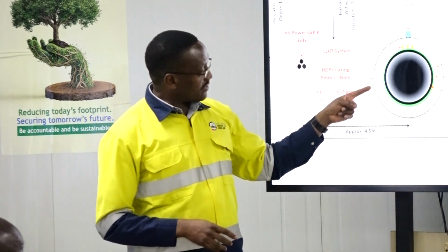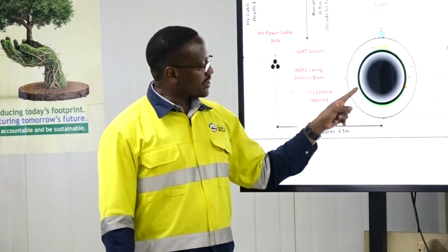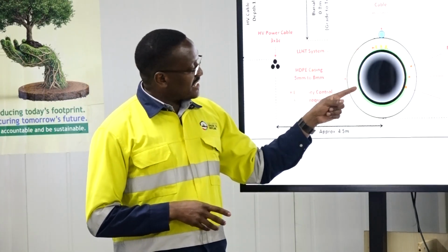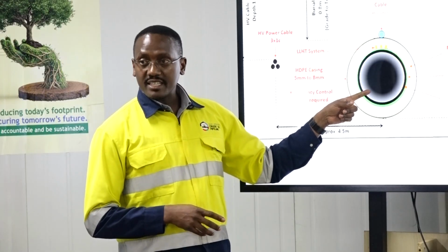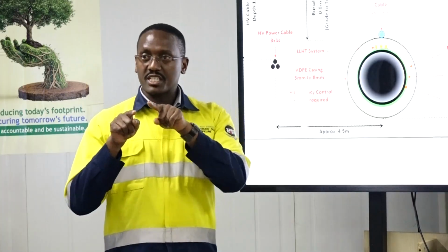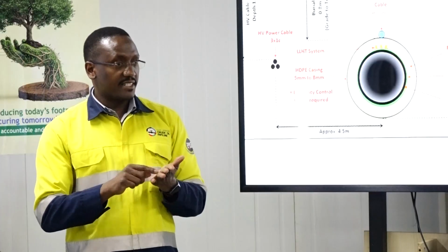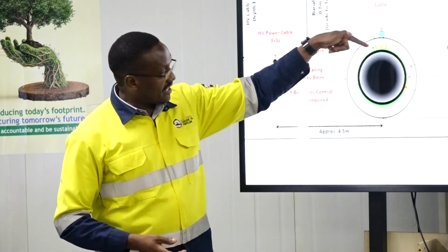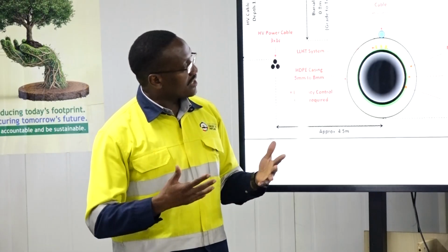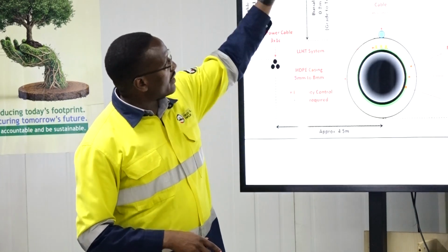So the pipes come, it's steel. It is coated with fusion bonded epoxy, again to help with corrosion. Then to heat the pipe and the oil so that it can flow, we have heat tracing systems. We have 3 raceways through which electrical cables pass, just like a coil for the flat iron. This will heat that and keep the oil at a temperature above 50 where it flows. Then the pipe is buried, like you can see.